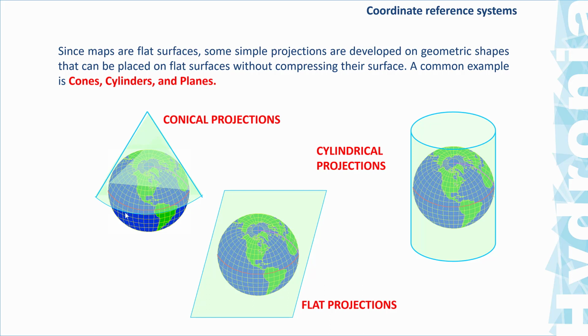projection. There are many different types of projections, mainly conical projections, where the sphere is projected on a cone, and that may be applicable to some areas. Then you have flat projections, that is just a plane, or cylindrical projections that also are used in some latitudes. Some of them are better represented for mid-latitude or for extreme latitudes, or for low latitudes, the cylindrical projections.